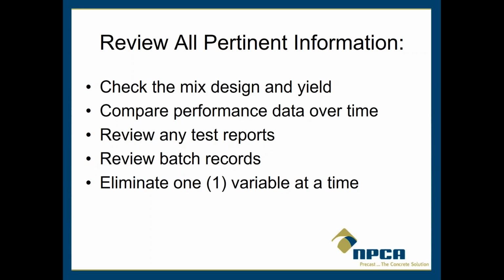And then, do I have performance data over time? It's always good to have control charts, both for slump, strength, unit weight, and air contents. If I can track those 4 things over time, then I can get a very good picture of how the mix is performing and when that performance changes.